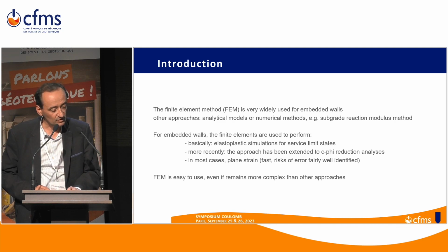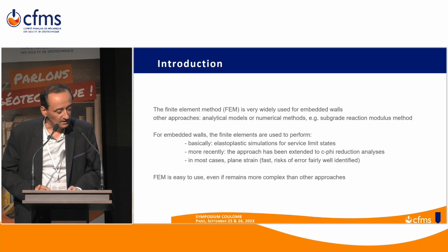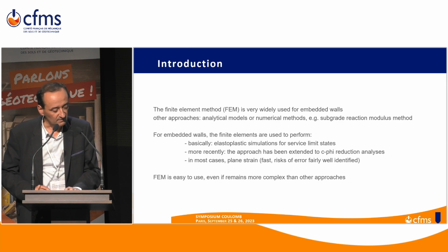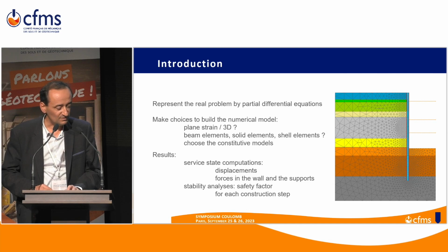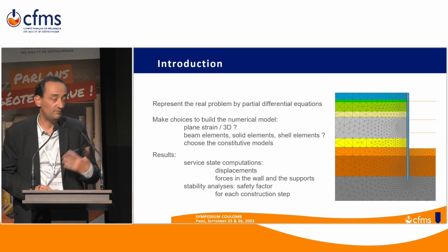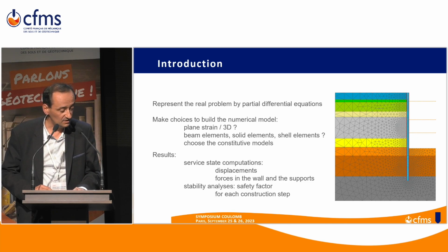In most cases, we remain in the framework of plane strain analysis, which means that the computations are reasonably fast, and the risks of error are rather well identified. So the finite element method remains relatively easy to use, but it's more complex than other approaches, you can say. The idea is to represent the real problem by a set of partial differential equations and to solve them numerically. So you have to make choices to do so. You have to build a numerical model, and you have, for instance, to choose between plane strain and 3D. And as I mentioned before, mainly we use plane strain.